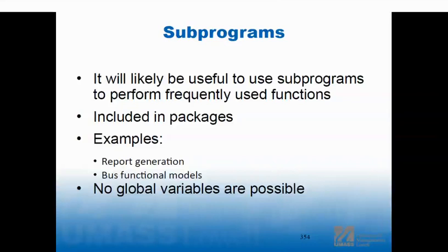And I surely didn't put requirements on the homework, but in homework 4, you wrote a few bus functional models. And in reality, I would have liked you to write those in a package. That package would be the package for that DUT, meaning it had all the interfaces that DUT needed. If I had a different DUT, it would have a different package with a different set of BFMs. Some the same, some different. And so that would be your package for the bus functional models.